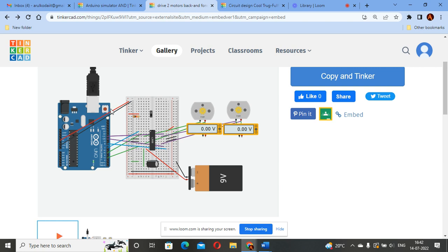Whenever you switch on and enable the forward, and give the signal, it will increase the signal, which is right rotating, then there is a delay and an off condition, and now it's going to move in the left rotation. This we can do with switch conditions or automatically. So this is the exact output.